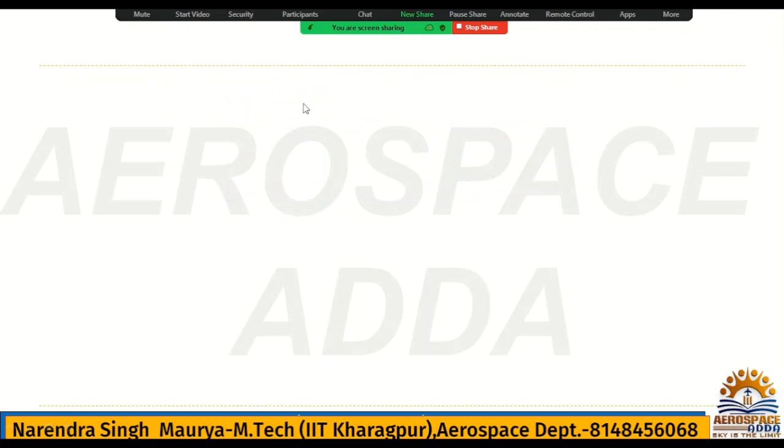All right, ideal ramjet. What is an ideal ramjet? What are the conditions? What was the outcome when we went through the ideal ramjet? Basically, for the ideal ramjet, most importantly, the inlet Mach number is equal to the outlet Mach number.